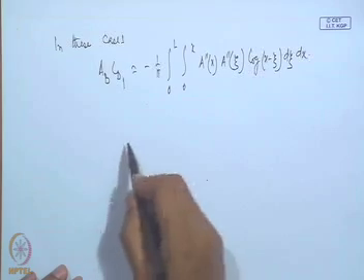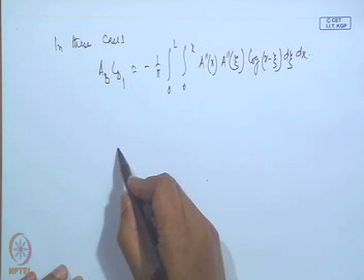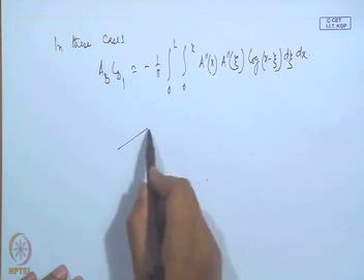Now, this simply implies that drag coefficient will not change if the base cross sectional area is not changed. That means, if the base is extended or rather if there is a shoulder and subsequently a constant area part of the slender body, then that uniform part of the body does not contribute to the drag coefficient. That is, if we have say, think about a cone cylinder.